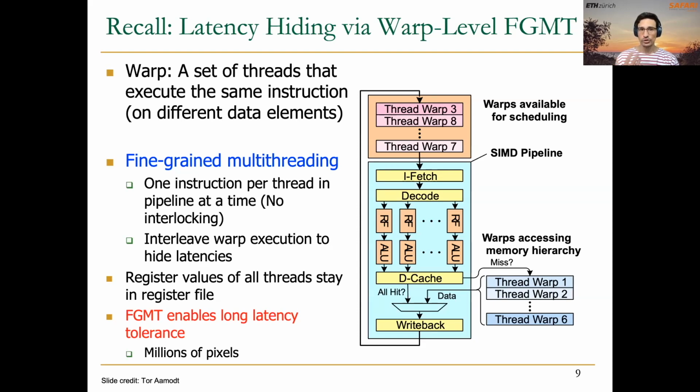The good thing of using this fine-grained multi-thread technique is that it's possible to hide long latency operations, such as accesses to the external off-chip memory, or some execution of instructions, for example, transcendental functions that are executed in the special function units, and they usually take longer than the execution of integer or floating point multiply accumulate